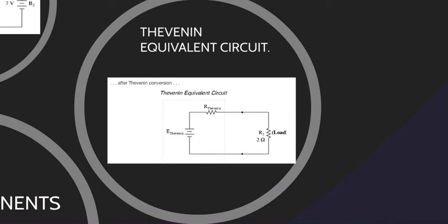This is the circuit, and it is the equivalent of all the components that we have seen before. If correctly derived, it will behave exactly the same as the original circuit formed by the other components. The load resistor, voltage, and current should be exactly the same for the same value of load resistance in the two circuits. The advantage in performing the Thevenin conversion to a simpler circuit is basically that it makes load voltage and load current so much easier to solve than in the original network.